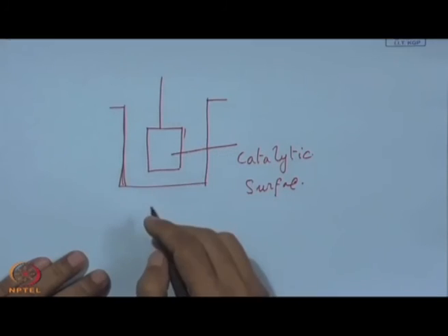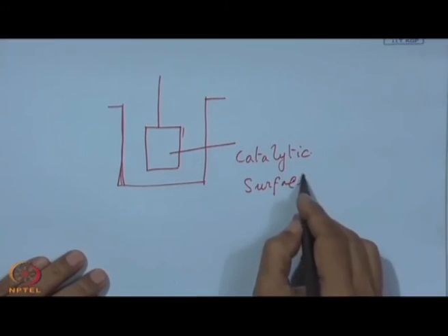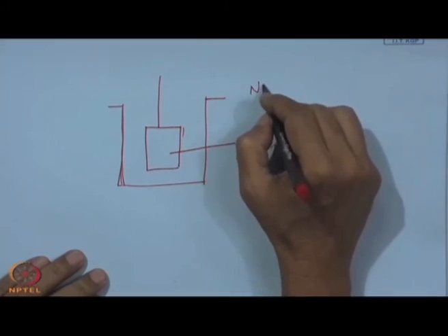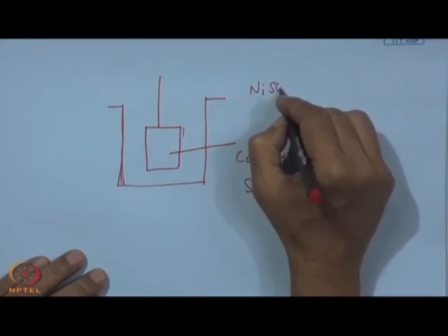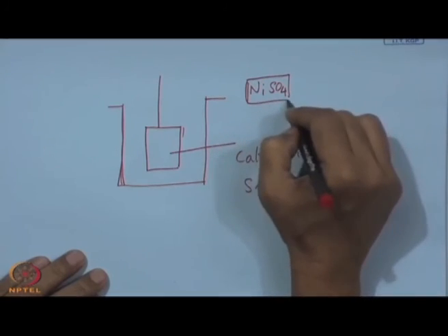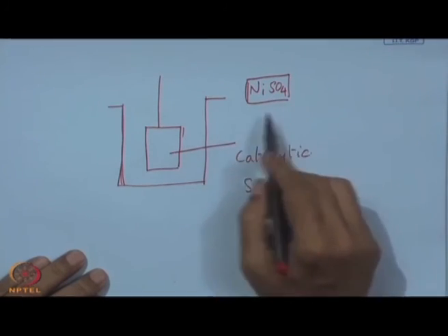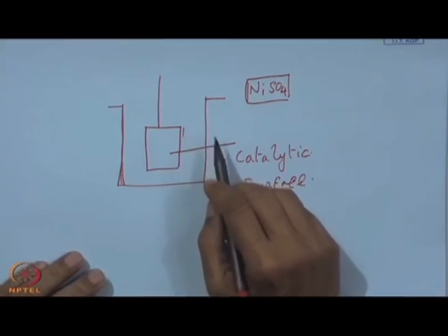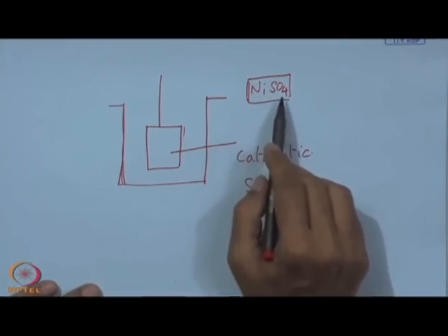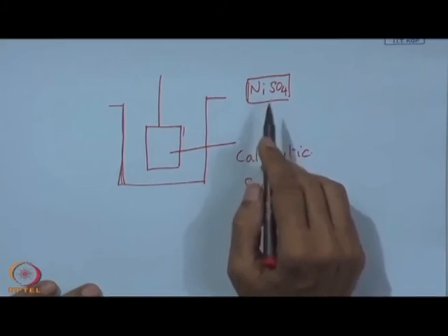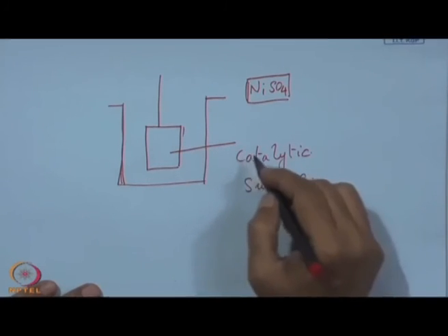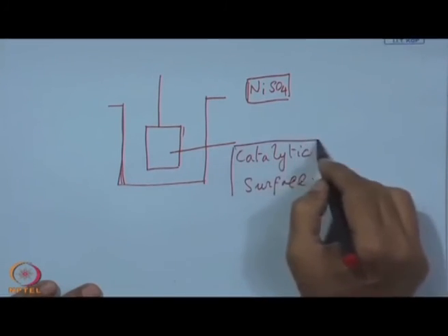Here we do not have any electrode, no supply of electricity is necessary. What we have is a nickel sulphate solution or nickel hypophosphite. Basically, sodium hypophosphite plus nickel sulphate is added, and the hypophosphite is actually a reducing agent. So, the nickel will be reduced from the sulphate, and this nickel will be attached to this surface. This will become a wettable surface, by this catalytic action.